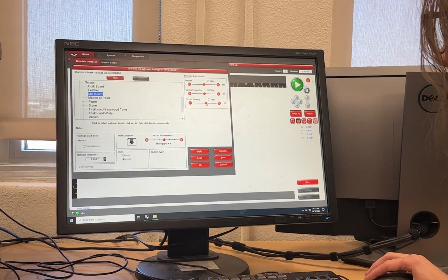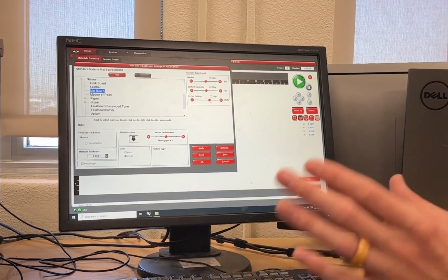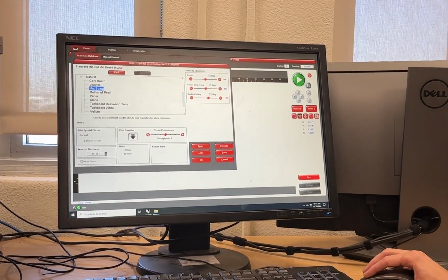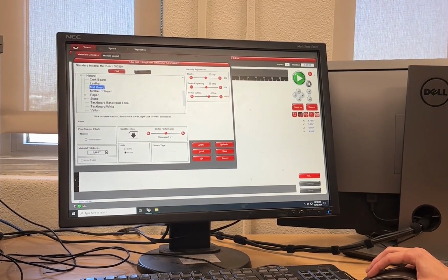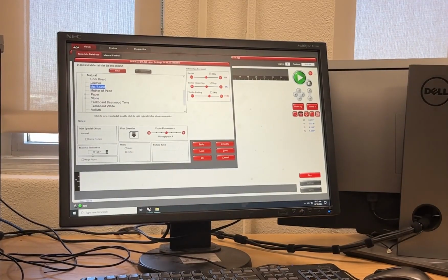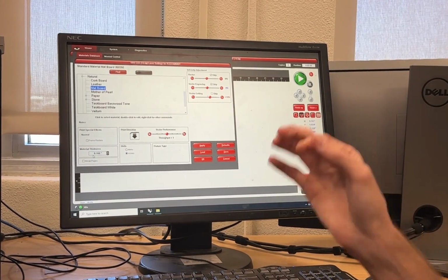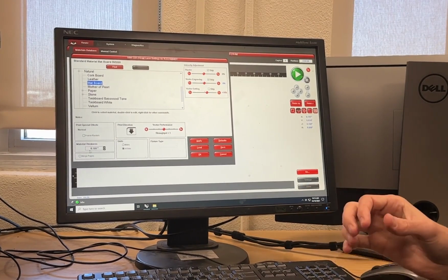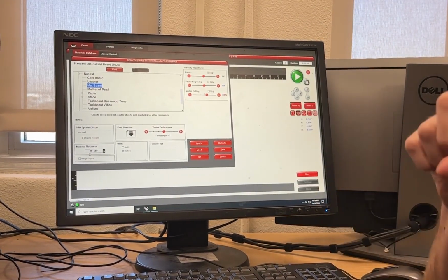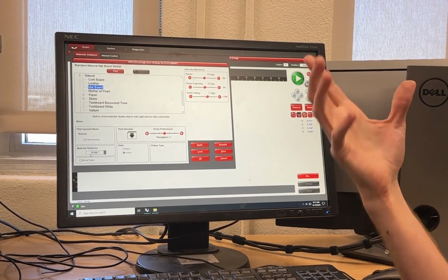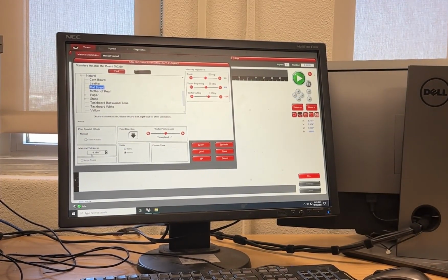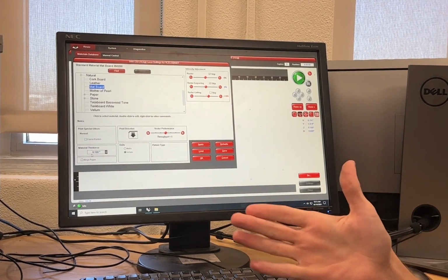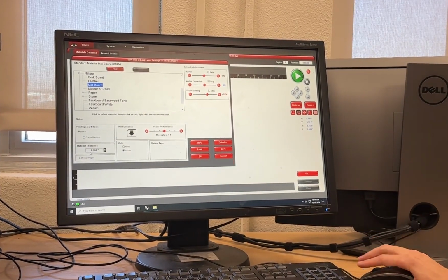And I can even decide to increase the power. Say it's not cutting very well, even though I'm at this mat board setting and I've got the right thickness, it's just not cutting still. I can add a little bit more power. I would go in sets of 5%, 10%, 15%, because to be fair, if you do 1% at a time, I don't really see the difference between 12 and 13, you know, and stuff like that. Usually I go 5 because you'll start to see the difference.